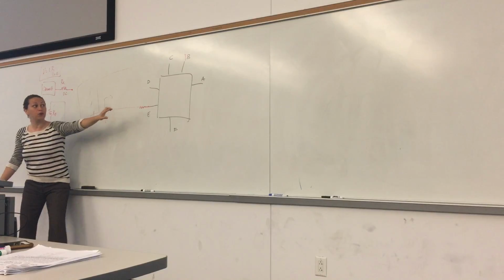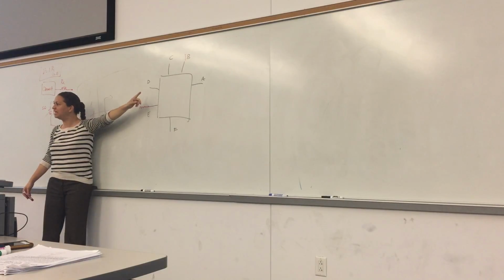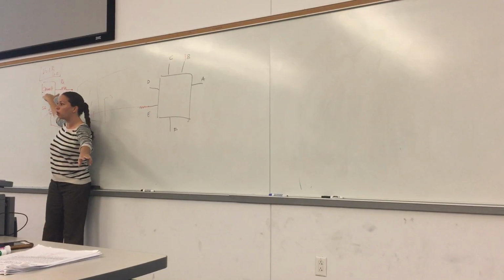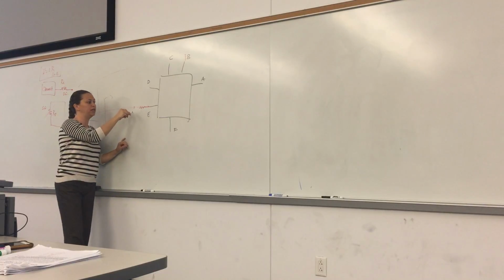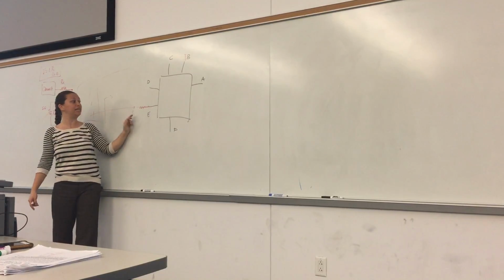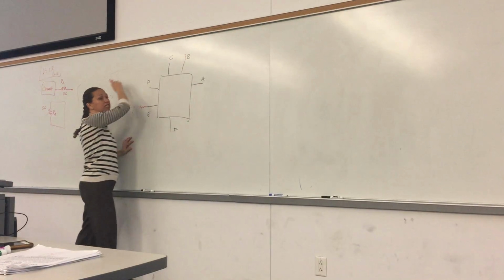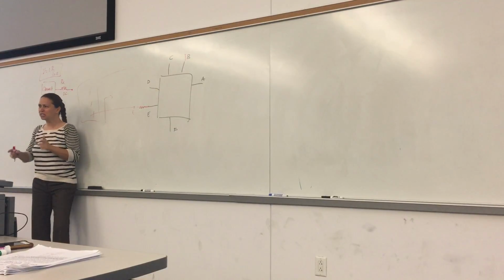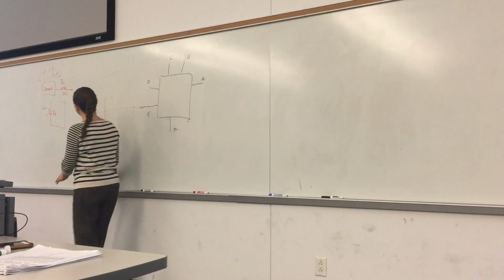So that's why, if you're looking at the circuit between terminals B and E, and there is a resistor floating at terminal D, you can say that this resistance is not connected anywhere, so it's floating, and you can ignore it. But if there's a resistor over here connected to terminal E, floating over here, but you're looking at the circuit between terminals B and E, then you cannot really ignore this resistor. Because the assumption is you have something connected to terminals B and E that's looking at the circuit problem. Okay? So based on that, please take a look at that problem while I draw it.